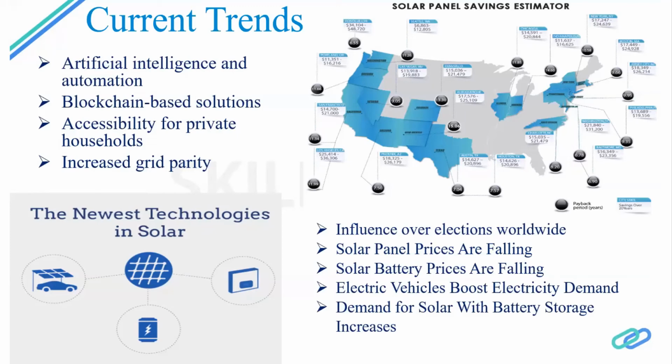Solar energy is very intermittent in nature. This means that solar panels produce power when the sun is shining and not when it is not. Energy storage allows the solar system to supply power during the night time or in cloudy weather, and that helps to expand the capability of the solar energy system. The two main types of solar batteries are lead acid batteries, like you have in your car, and lithium ion batteries. Lithium ion batteries are far more advanced, longer lasting and require less maintenance.